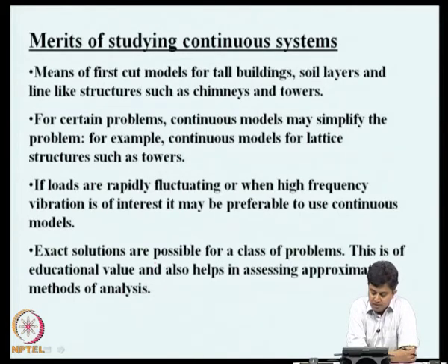For certain problems, continuous models may simplify the problem. For example, continuous models for lattice structures such as towers. A tower is essentially a lattice structure, but we can represent the behavior of a tower by, say, a Timoshenko beam, and then studying a cantilever Timoshenko beam is a lot easier than studying a huge lattice structure. Another thing is, if loads are rapidly fluctuating or when high frequency vibration is of interest, it may be preferable to use continuous parameter models than discrete models.